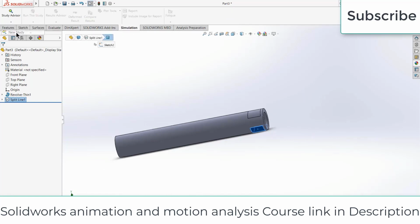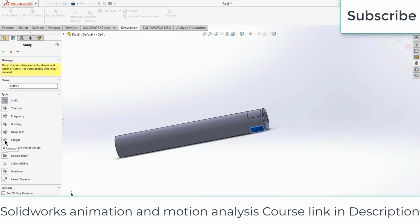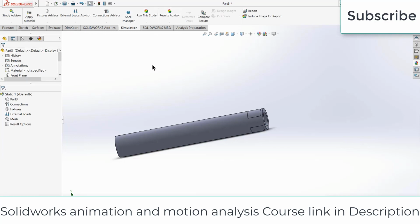Click here, click on new study. To do fatigue analysis, you first need to do a simulation. If you don't do any simulation, you can't use fatigue. So click on static and click OK, because first we are going to do a static simulation.